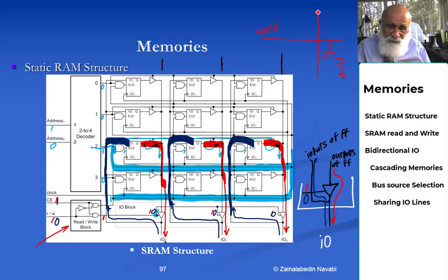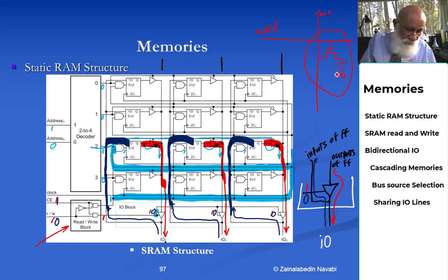This is the bit line, and again, there is a structure like this, except that the whole memory element becomes what I'm showing here in the circle. Let me draw it here. Capacitor, ground, word line. This is bit line. This is word line, which is the line coming from the decoder, and this is the entire memory element.